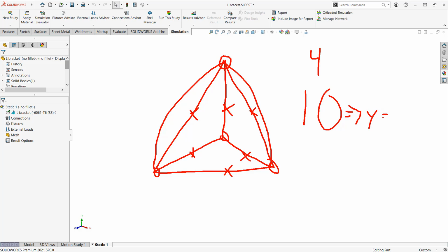Because it's a parabola, let's just do a basic parabola, y equals x squared. Here with the 4-node draft quality, we have the geometry as just a linear definition. You know, it always goes back to math, huh? So we're looking at the actual function defining the geometry. Now, this is important because this gets taken in as an input of simulation. And then we define the displacement of it. How does it change over a load, a pressure, a force, okay?